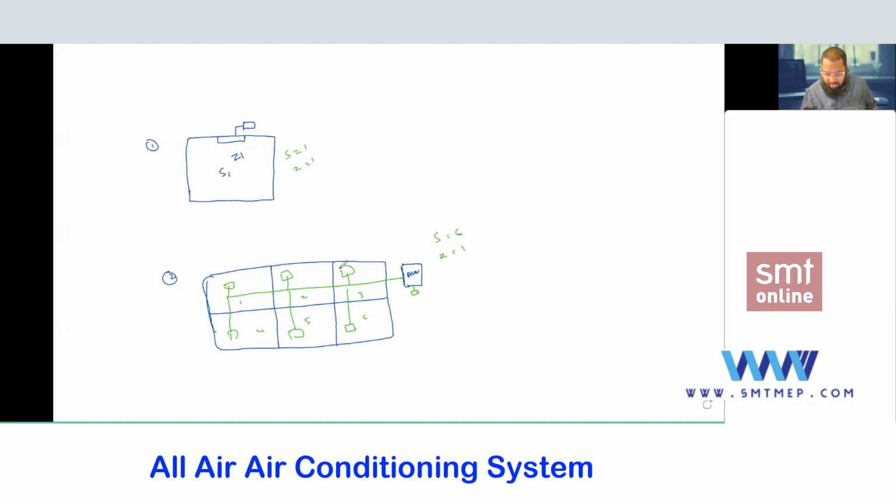And you can consider this like a CAV system, and whenever you switch on the unit, you'll get the flow rate from this diffuser as per the design. It will not decrease or increase, the same flow rate. So it's a CAV system, and CAV system we can call as single zone, because you see for all the spaces the thermostat is 1, so it's a single zone, right? So this is also an example for the zone. So zone, don't think that zone is always a set of spaces. It can be one space, one zone, or multiple spaces, one zone. Okay.